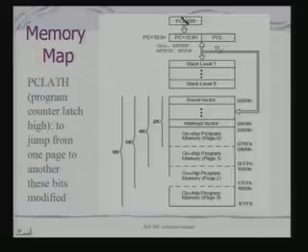This part is mapped to the program counter latch high register, and it is connected as per the architecture. Also, you remember it is connected to the hardware stack, and through the 13-bit bus it is connected to the register bank as well. What I have shown is the individual pages, which are of size 2K. And the first page typically has your reset vector and interrupt vectors.